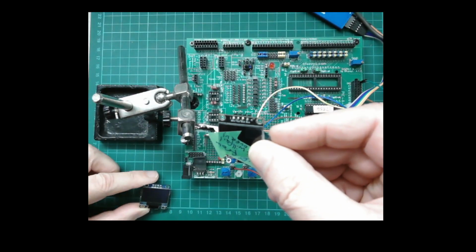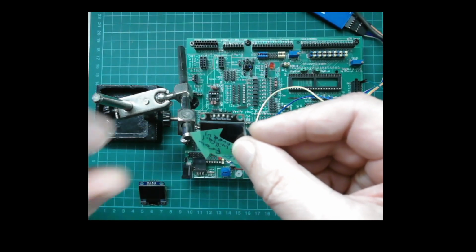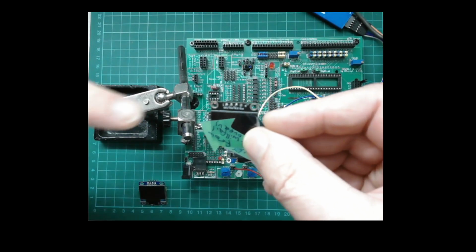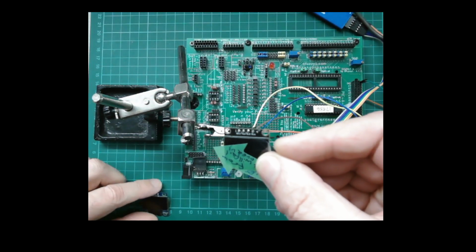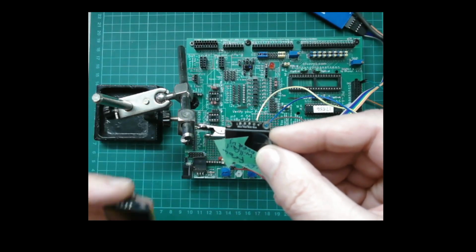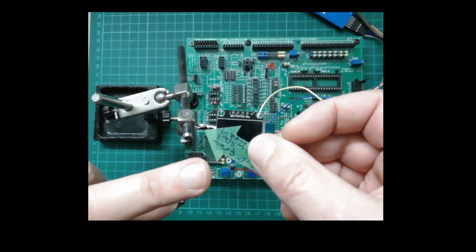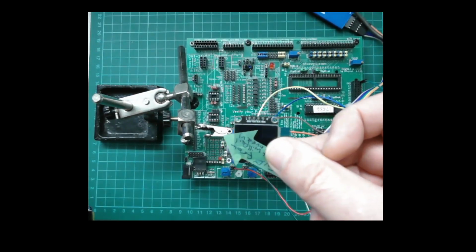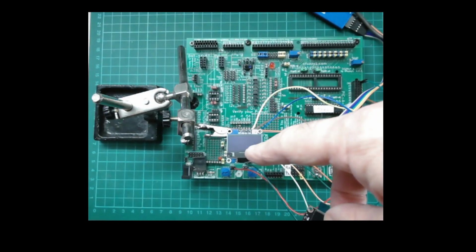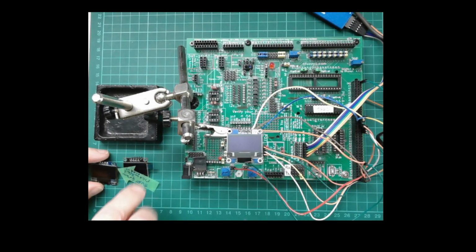They are very different. This one has the ground as pin 1, then the VDD, then the voltage, then the SDA, and then the clock. So in this one, it's inverted. The voltages are inverted. So this one is VCC and ground. Then this one's ground and VDD. Isn't that great the way they're labelled? This little yellow thing here tells me not to put more than 3 volts into it. More than 3 volts blows this thing up. This one is 5 volt tolerant. When you're doing I2C, you have to be aware of the power.